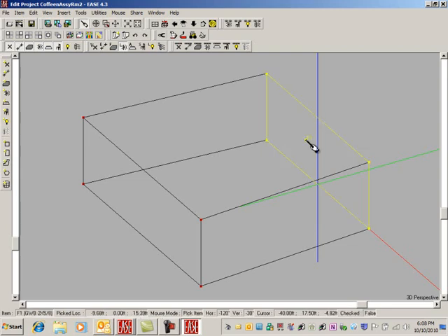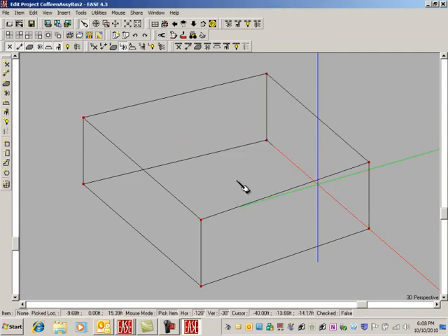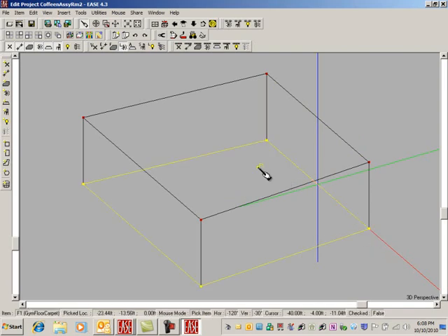Now, I know that the lip of the stage, the apron of the stage, is up 2 feet off the floor. It's not a very tall stage. What if I took this guy and I duplicated him vertically, Z 2 feet? Okay. All right, that's done. Now I can see I've got the makings of this stage apron. If I ever want to zoom in, I can just come over here and zoom in like this. I can see things better.